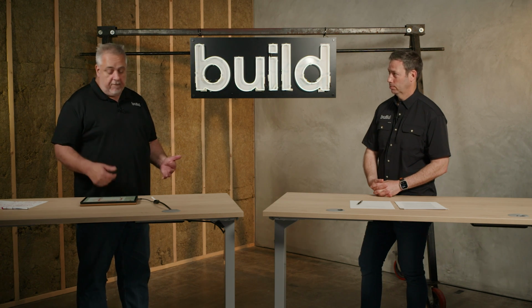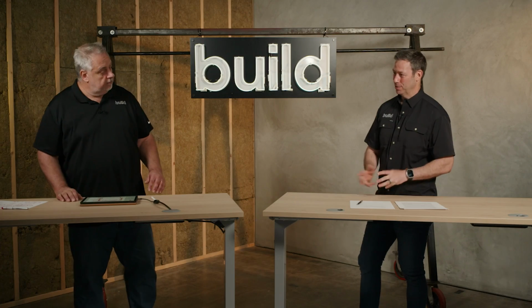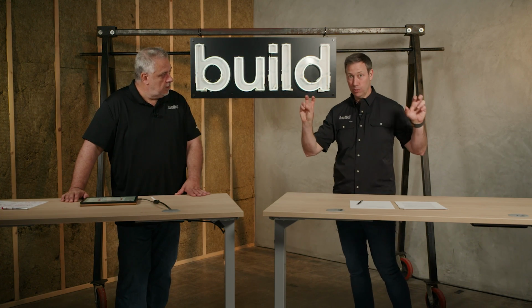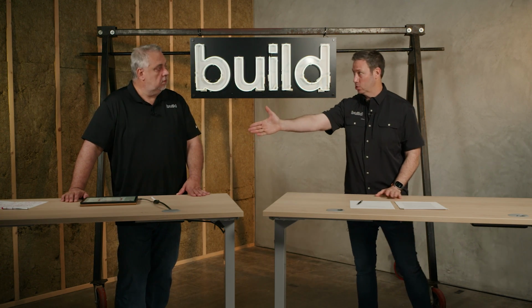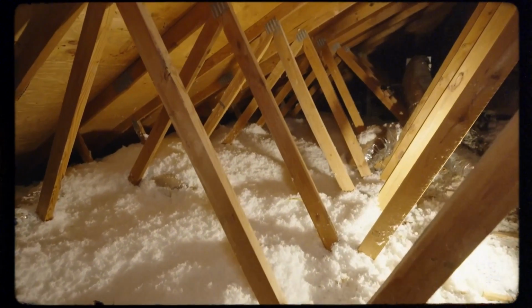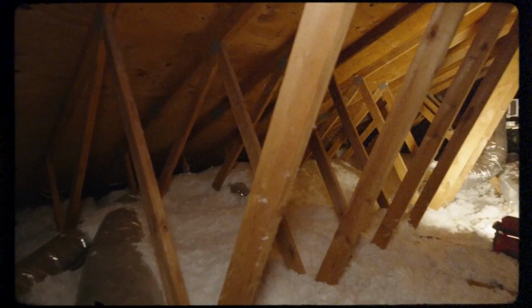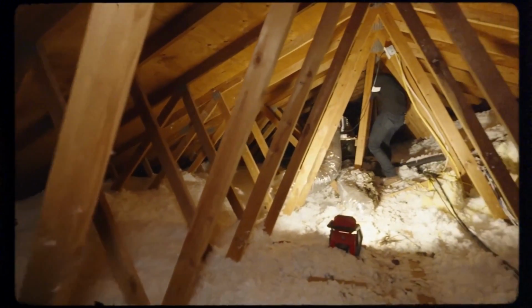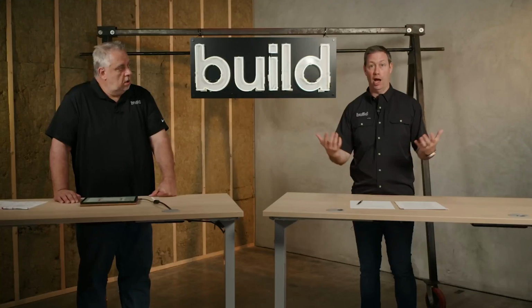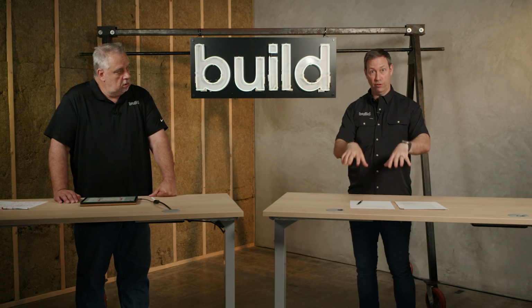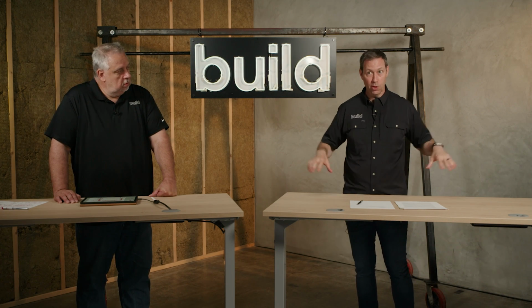If I can't define whether my attic is outside or inside, then don't even come to me thinking about control. Because you don't even know what you want to control. And as a further note on that, if your attic is outside, meaning the ceiling is your air barrier, and that attic's outside, where I am in Texas, we see a lot of mechanical equipment up in attics, which are outside, meaning it's a vented attic. You see these air vents. It's a pretty hot space. There's insulation on the floor of the attic, and the drywall is the air barrier.